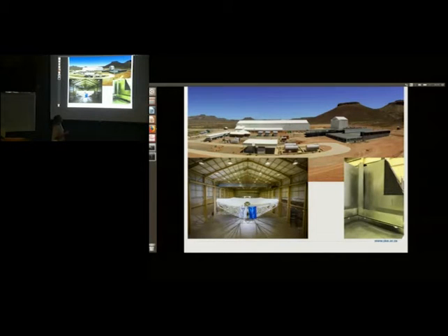And this over here is the Karoo Array Processing building, which is the Faraday cage that houses all the electronics on site. During the inauguration, there was a small model of what the interior of the KAP shielding room looks like. You can see the honeycomb structure over here. This building is also built into the ground, approximately 1 story level deep. You can't see it in this picture, but there's a heap of ground that also provides another 20 dB of shielding for the telescope.